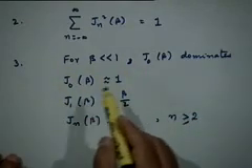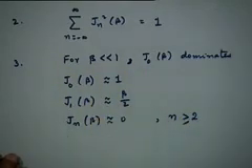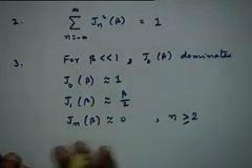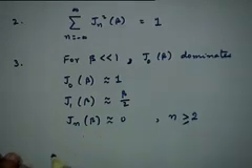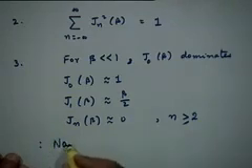Which is very interesting, because it is precisely these spectral components which are present in the AM signal. So when the modulation index is very small, the spectrum of the FM signal is very similar to that of an AM signal. There are some important differences which we will come to. So we call this kind of an FM signal or PM signal narrow band angle modulation.